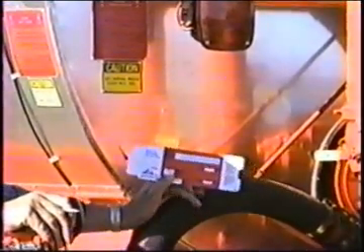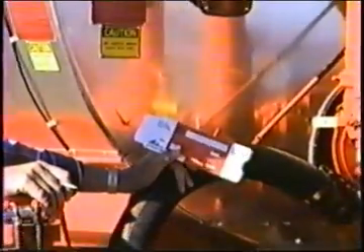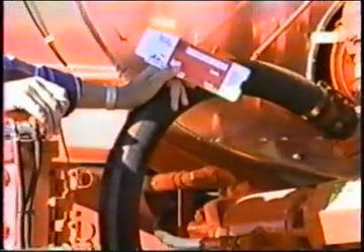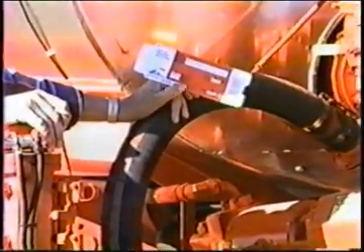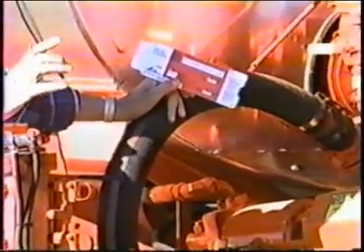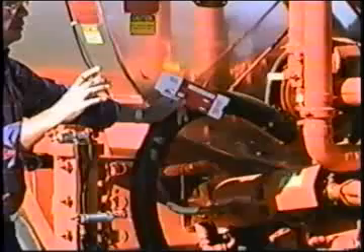That is, we could get out the slide rule, or if the truck is not computerized, there would be a pressure gauge on the control panel that shows the actual spray bar pressure. Okay, as we hold 400 feet a minute and we read the actual spray bar pressure gauge, we would read 8 pounds.